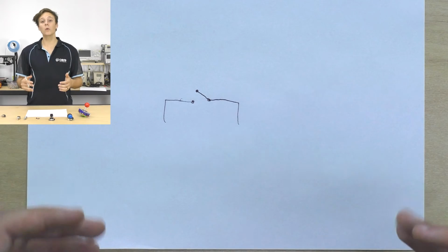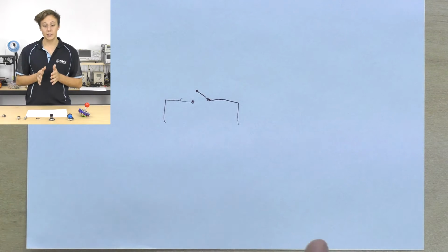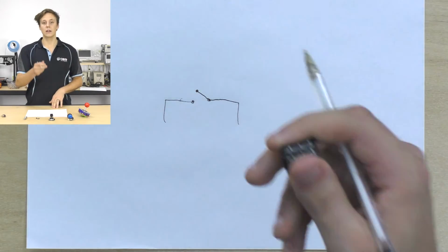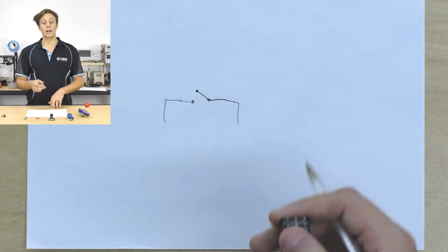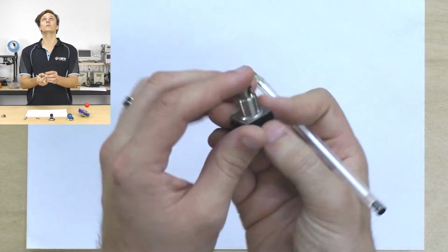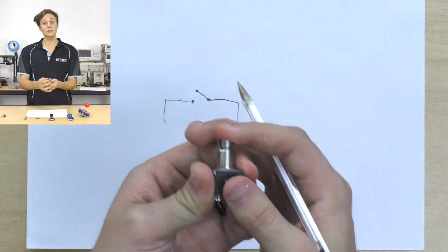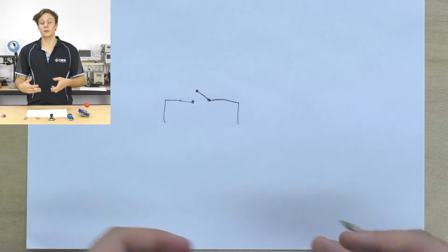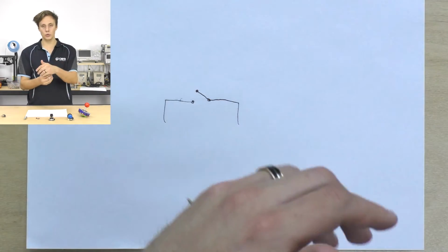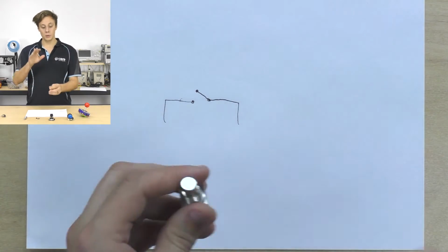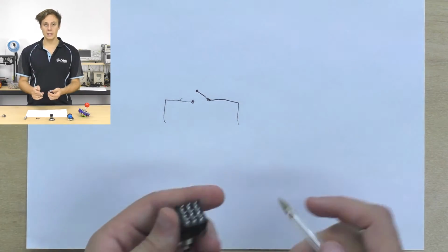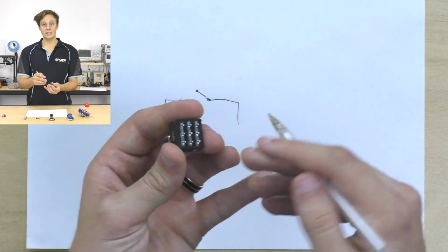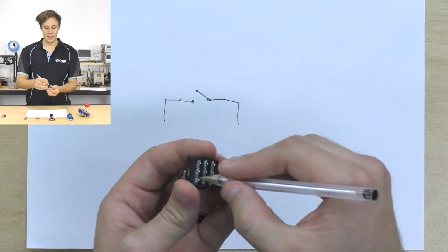As we said, the pole is like an isolated channel. Take this switch here, for example. This is a triple pole, 3-pole, double throw switch, and it's a foot switch. It's designed for industrial applications, but most commonly for audio effect circuits, so guitar pedals and effects pedals, where you need a really durable switch with a nice tactile feel that you can press under your foot. It has 3 separate channels, which means each one of these pins is isolated from each other, and they each have their own throws.